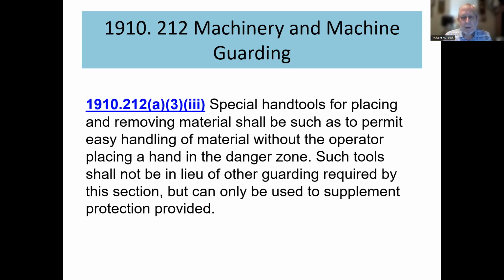So special hand tools for placing and removing materials shall be such as to permit easy handling of material without the operator placing a hand in the danger zone. Such tools shall not be in lieu of other guarding required by this section, but can only be used to supplement protection provided. So they're saying you can't just have it unguarded if you have a tool to push a part, let's say, into the point of operation. You should still use them, but it doesn't get away from using guards.